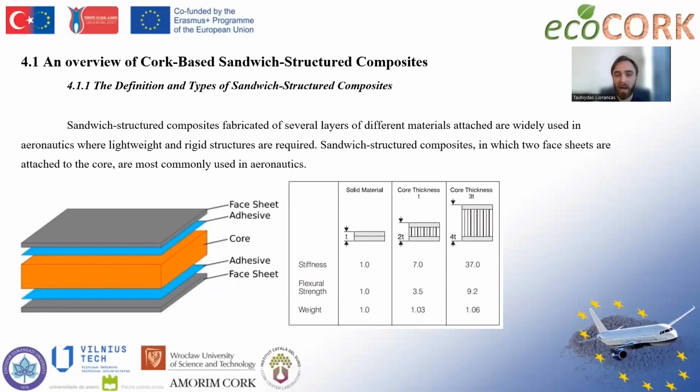To understand the reason why it is so commonly used in aeronautics, we should look at the picture on the right, where we can see that by making a sandwich structure, we increase the weight of the material very slightly, but we can increase the stiffness very significantly.